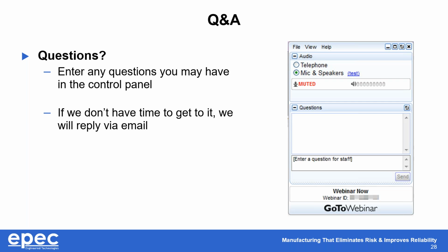So how do we test for this? We'll set up a jig and do cycle testing. We'll use our ESS chambers and other thermal chambers to run thermal shock, temperature cycling, and other testing to stress a device. We'll set up a little counter and a little pneumatic piston to go press a button 100,000 times and make sure that it's still falling in spec for switch bounce. So it really depends on the technology, but there's a lot of options that we have to test for long-term reliability.